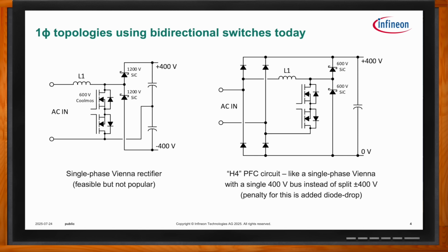All right. So, Eric, are you seeing these topologies being used at low power levels or high power levels or both? Well, so these are both single phase input, and typically, it kind of depends. If we're talking about a home consumer marketplace, you're limited to whatever 80% of the breaker rating. So in that sort of setting, you'd never see these over maybe 1.5 kW. Like I mentioned, in the data centers, maybe up to 3 kW. But now we're seeing the trend in data centers to much higher power levels thanks to the proliferation of AI.